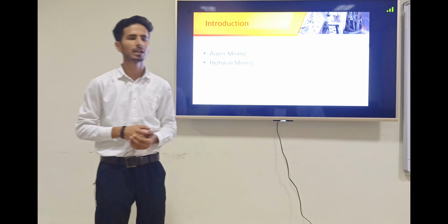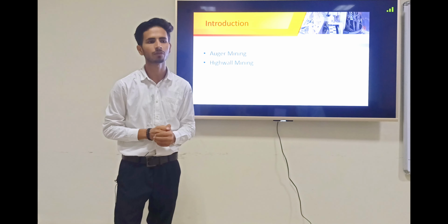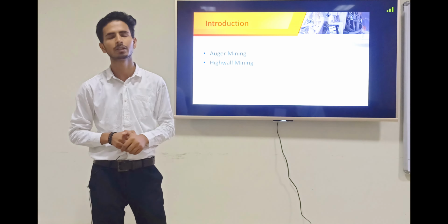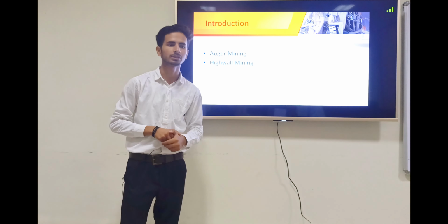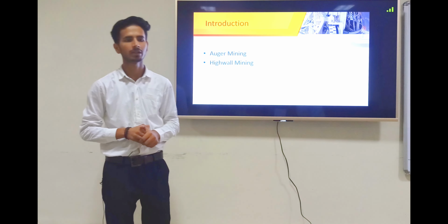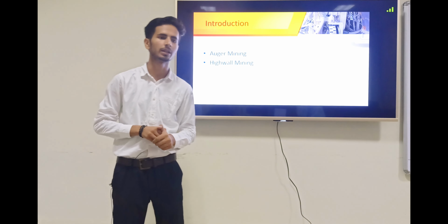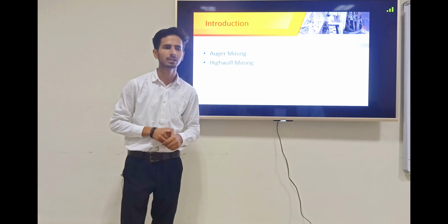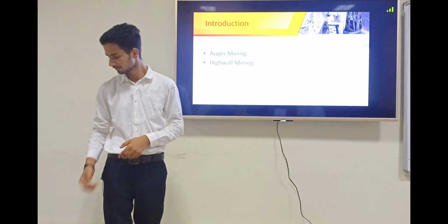High wall mining is an adaptation of auger based mining. Instead of an auger hole, an entry into the coal seam is made by a continuous miner remotely operated from a cabin at the surface. The cut coal is transported by conveyors behind the miner to the outside. Using a television camera, the operator can see and control the miner's progress.